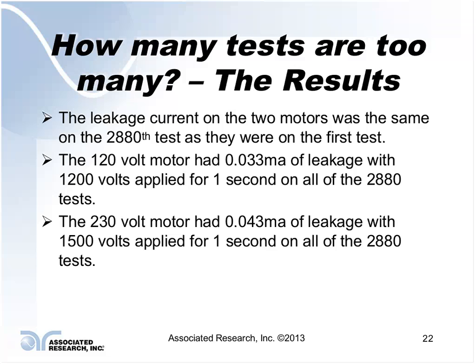People may come back and say, well, hey, here's some examples. I've tested my product here at the factory, I sent it to my customer, and my customer tests it and fails the product, and now he's sending it back to me because it failed the Hipot test. So, yeah, repeated Hipot testing is destructive. I've gotten those calls, and I've tried to evaluate some of these potential problems.